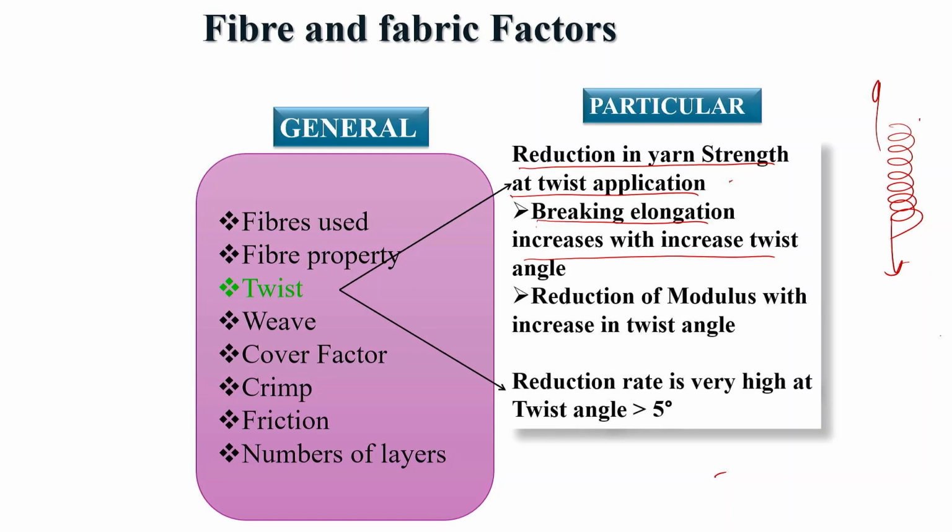One contribution is the extension of the fiber, the individual filament will get its extension, but at the same time, due to the helical structure, when the load is applied, this helical structure gets straightened out, and that will add to the breaking elongation.